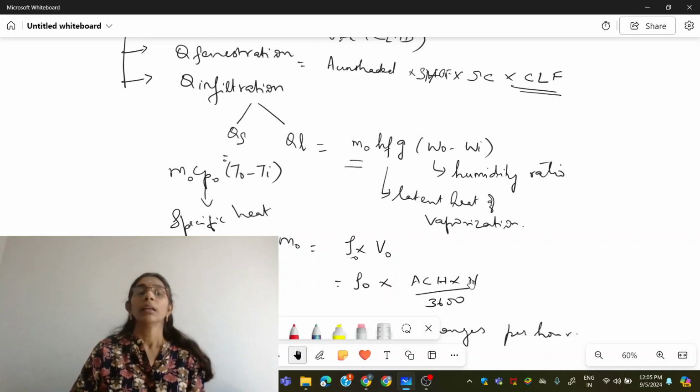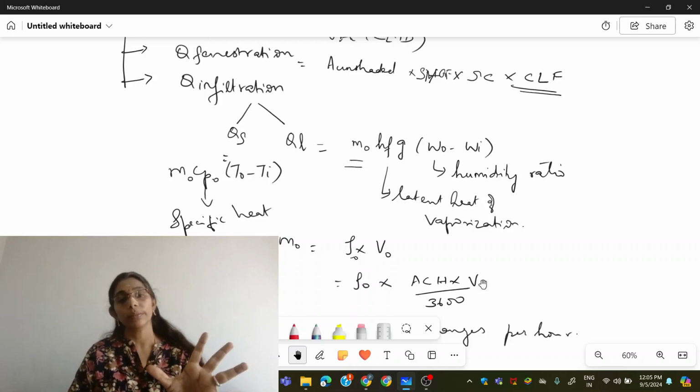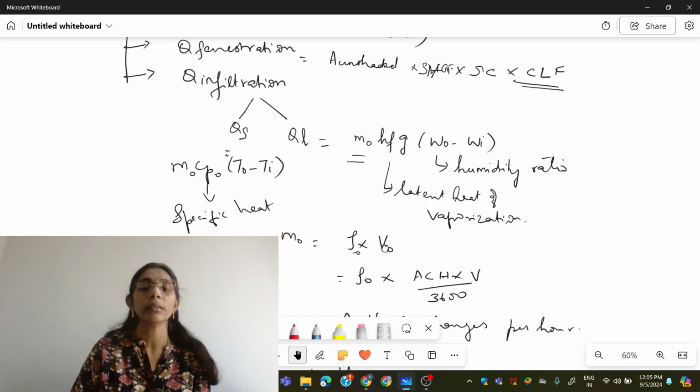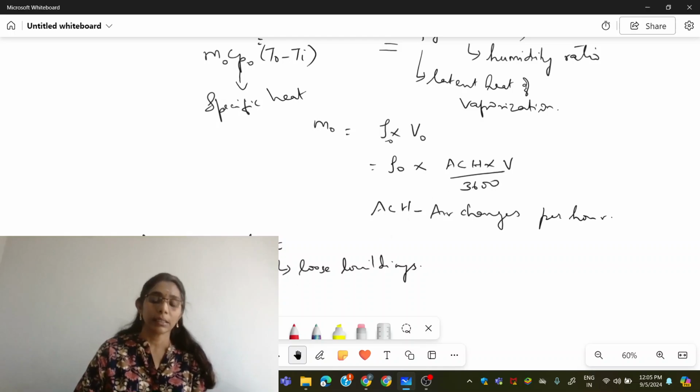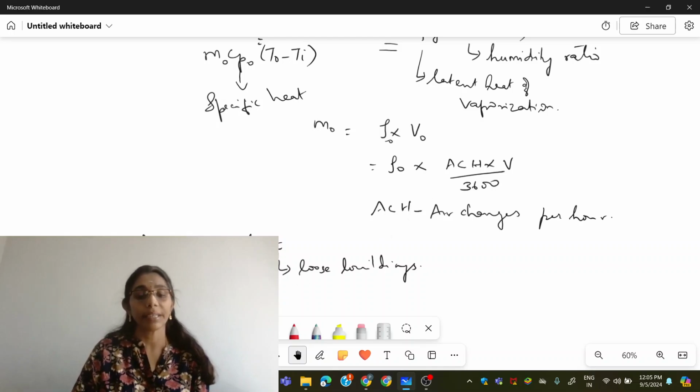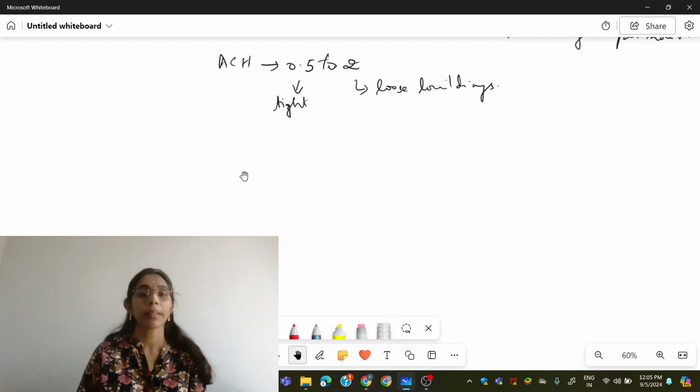Now, here you have seen V. V is nothing but the entire volume of space in the building. Say it's 3 meter by 2 meter by 2 meter, then it is 3 into 2, 6, 6 into 2, 12. So this V will take the value 12. And we have seen what air changes per hour is, and it takes a value between 0.5 and 2, right? Now, we are done with this.